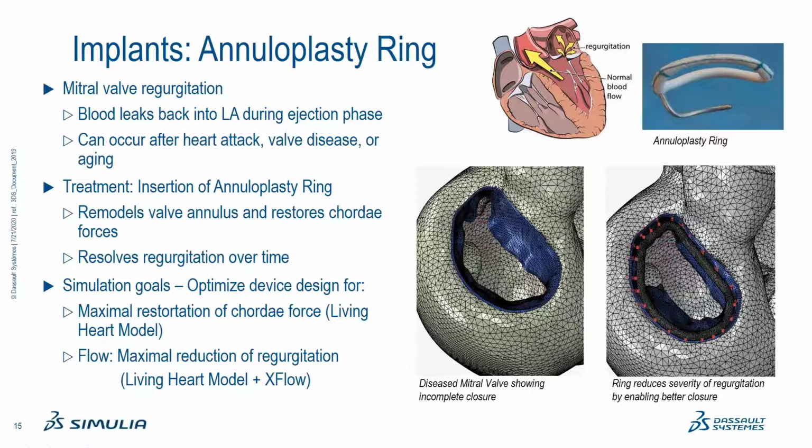This is a challenging fluids problem to simulate for two very important reasons. The valve leaflets are moving very large amounts, making conventional meshed fluid methods very difficult to apply. And the blood flow is being pinched off, a condition that is not possible to accomplish with meshed methods.